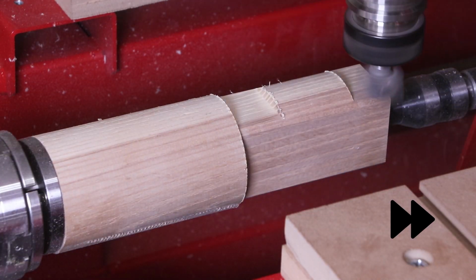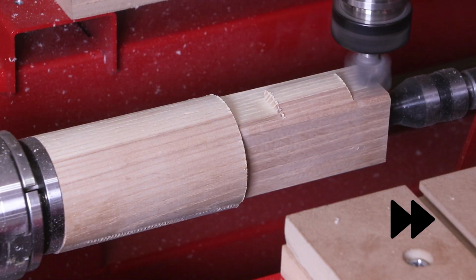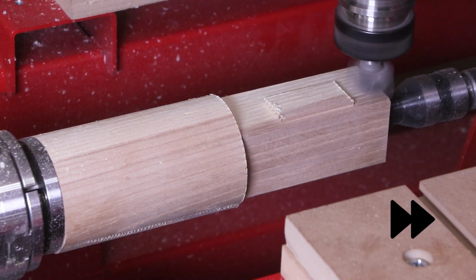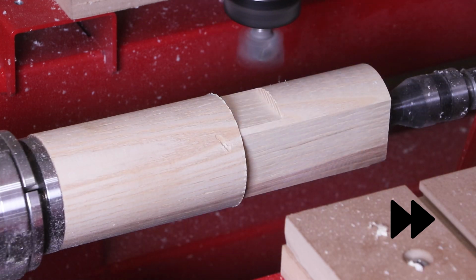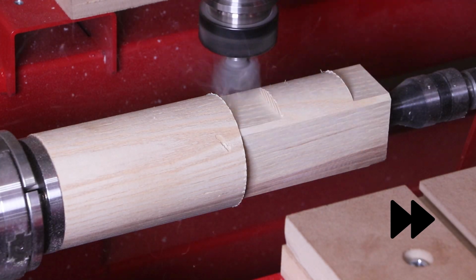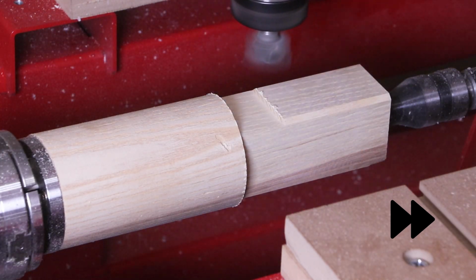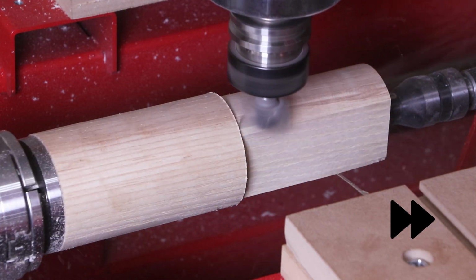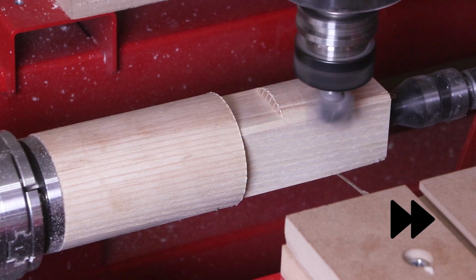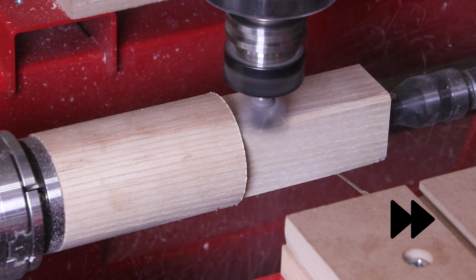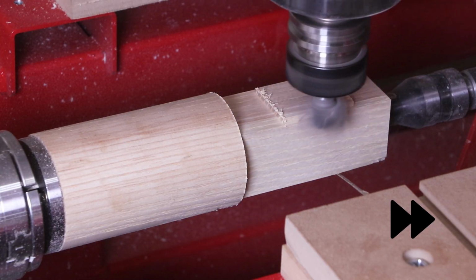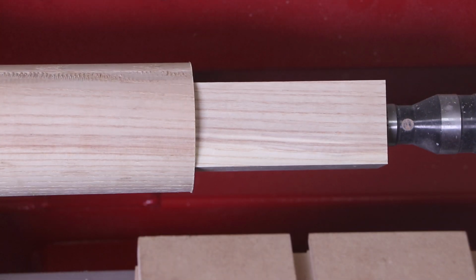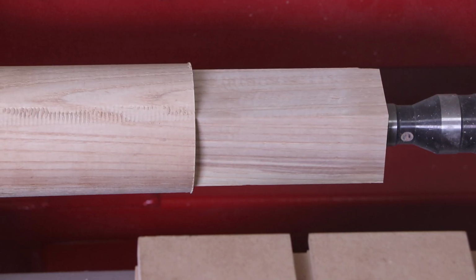After this surfacing technique happens twice for 2 different cut depths, the cutter moves out of the way so the part can index to the new surface and repeat this process for all 4 sides. All the cutting advantages shown throughout this cutting demonstration are automatically implemented into this Indexing Multi-Sided Cut toolpath in Conversational Cam Pro. You now have a basic understanding of how to use the Indexing Multi-Sided Cut toolpath. Go out and give it a try yourself.